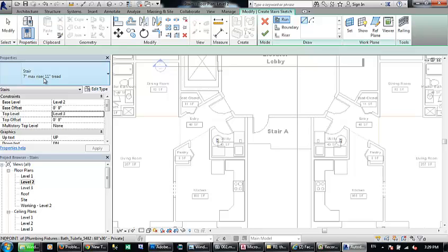So Revit in this case will approximate it to 3, and then it will make 20 inches over 3, and this will equal the stair height. So it will set the stair height in this case as less than 7. This is why it says 7 inches as maximum. So in this case, the stair height will not be 7, it will be 6.8 or 6.9 or so.